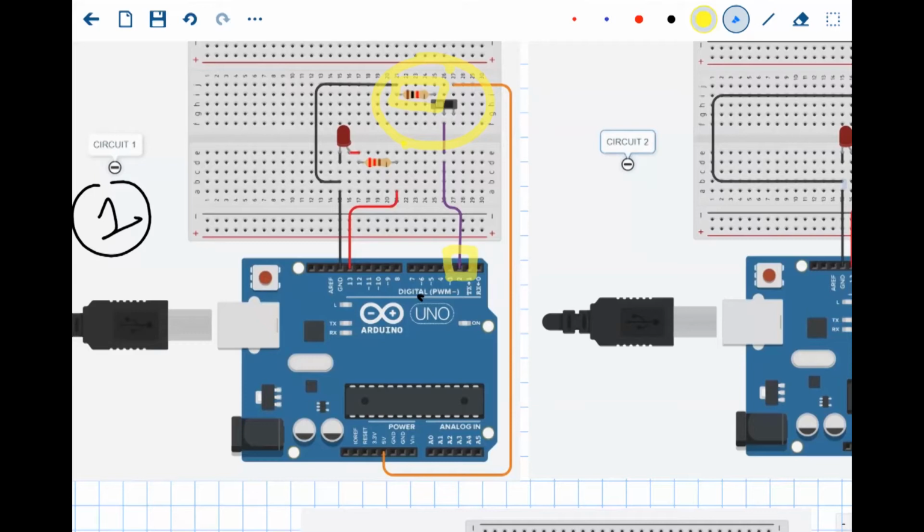This is not required for PLCs. For a PLC, it is on, and if you remove the wire, if it is floating, it is considered as an off. It has internal pull down resistors. So this is one of the things, again, Luke, which makes the boxes different, because typically those boxes have either a pull up or pull down kind of system, and which hampers a bit of flexibility.